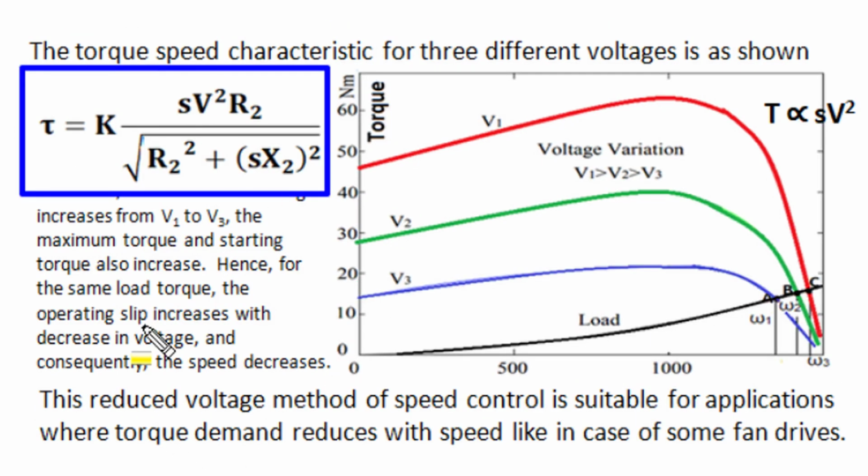For an induction motor of fixed per phase rotor resistance and fixed per phase rotor leakage reactance, the starting condition slip is 1 and constant, so torque is proportional to applied voltage square, and similarly the slip of maximum torque is also fixed, SM, so for a fixed value of SM again torque is proportional to V square.